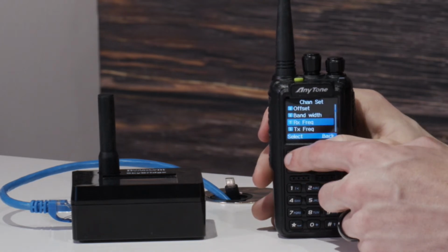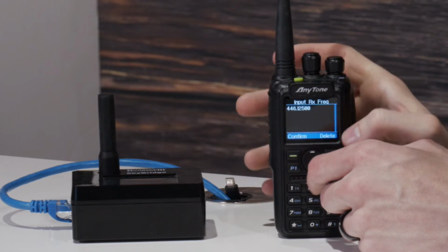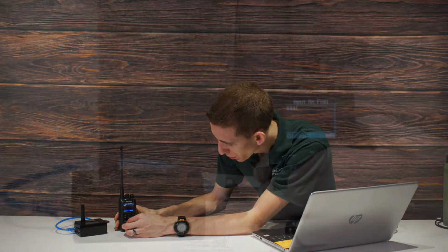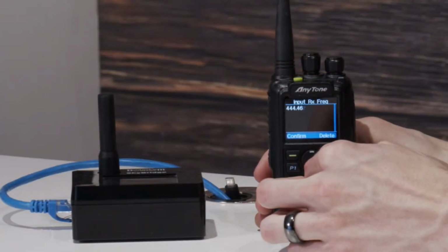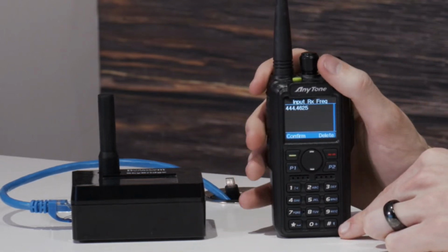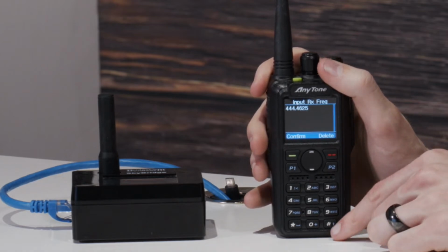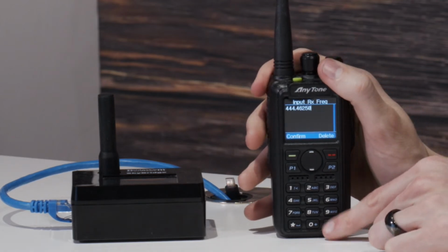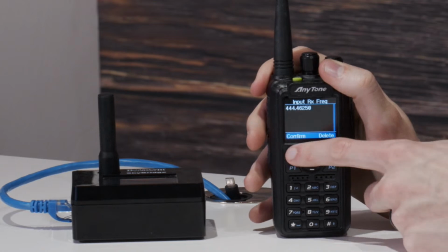Awesome, here we go. So we have our receive frequency and transmit. So we'll go ahead and delete what's in there. Now, keep in mind, we have uplink and downlink. So receive on the radio is going to be the downlink from the repeater. So downlink is 444.4625. And it'll automatically put that period in there for you. Now, one thing to keep in mind, once you type in that number, you can either finish out the zeros if you know how many you need, or the best way to do it is just hit the pound key and it will complete it for you, just like that. Click confirm.